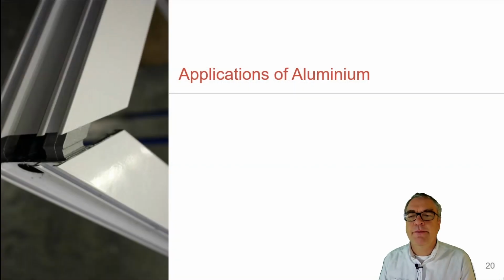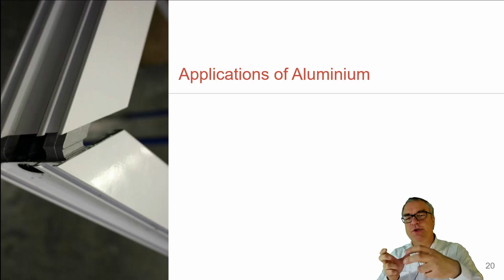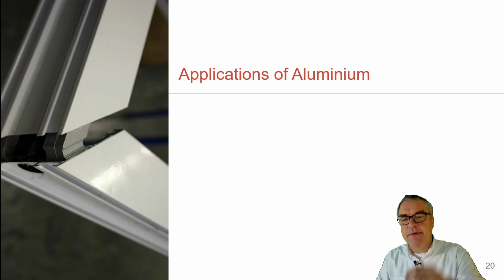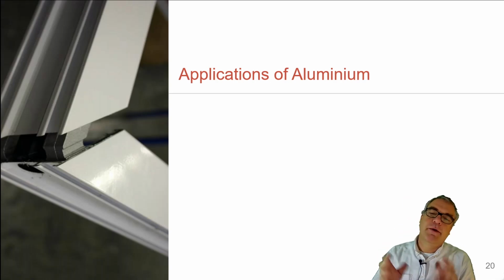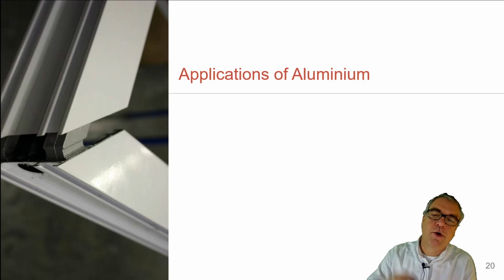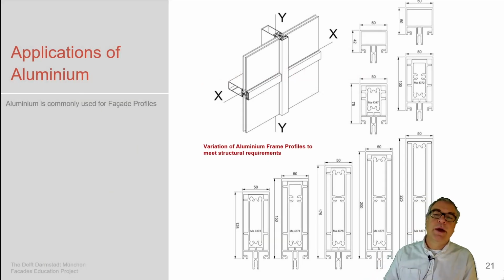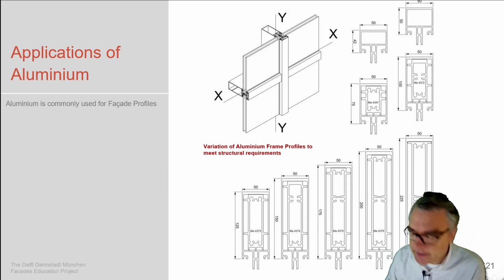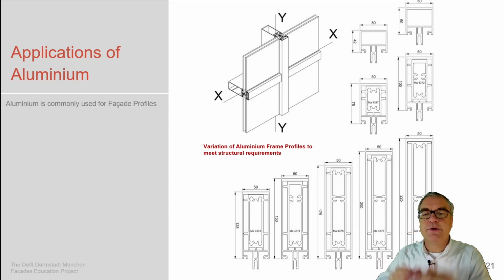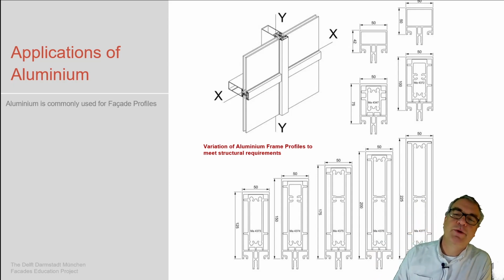Applications for aluminium, as I said, these super nice sharp profiles. If they're expected to be a window, we see a corner cleat connection happening here. Then they're cut at a 45-degree angle and then brought together. The profiles which we use are these. So this is one aluminium provider.